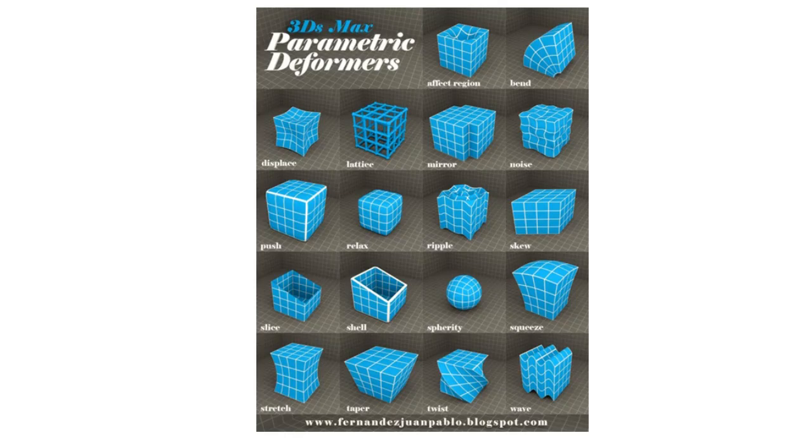In this lesson, we got acquainted with just a small group of modifiers that work with standard and extended primitives belonging to the Object-Space Modifiers group. Some groups of modifiers work only with editable poly objects, and some of them work only with splines and NURBS objects.